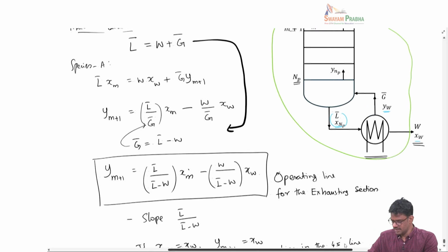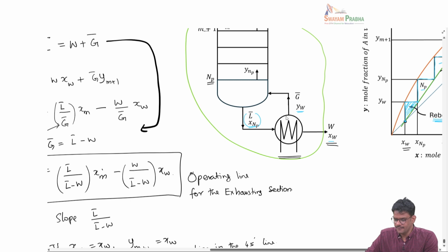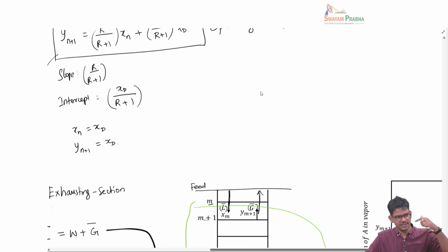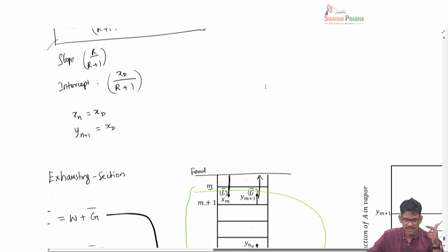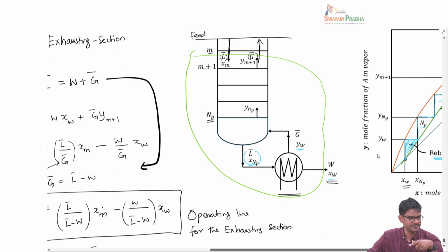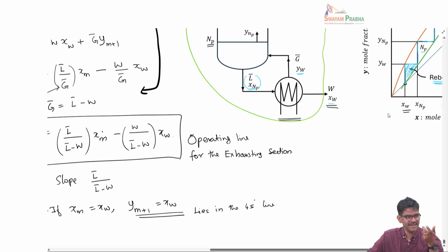You're asking why we have not introduced a reboil ratio for the reboiler. That is not needed here because setting the reflux on the top and the reboiler duty will automatically set this. Here the reboiler, as I said, is a flash device. By controlling the heat input, I can change how much vapor I am creating.